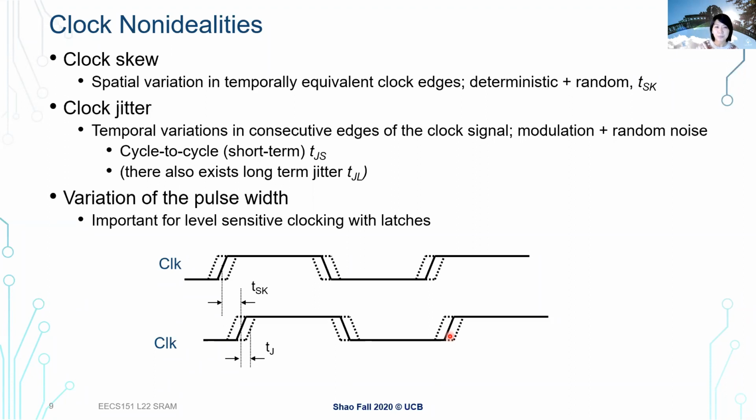You will have multiple clocks. The worst case for the overall critical path would be that the first clock has jitter showing up later, while the second clock has jitter showing up earlier. So those are also related when we think about the differences between two clock signals, between two registers, because those are what we're interested in: how the signal is propagated through a clock stage here.